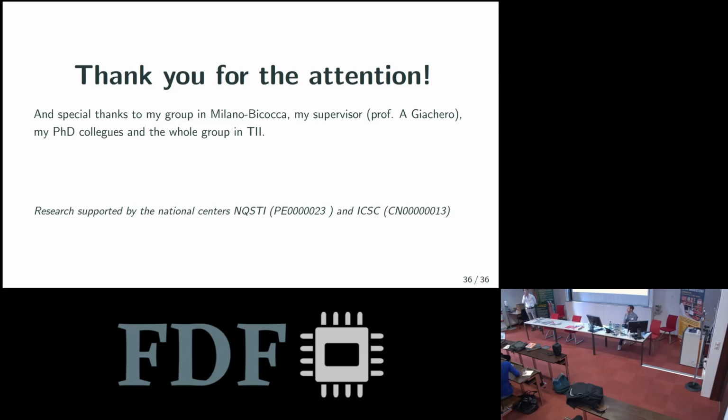Okay, well, it depends a lot on the design of the chip. Usually you need one drive line for every qubit, and the readout can be multiplexed. If the chip is designed well, usually you can use a single readout line for about 5 qubits. But with the 216, for example, which is a generation 3 RFSoC, you can multiplex much more than 5 channels, because you have a large bandwidth of 10 gigasamples per second. So potentially it's very scalable. But at some point you for sure need to use multiple evaluation boards, because 7 qubits is not so much.